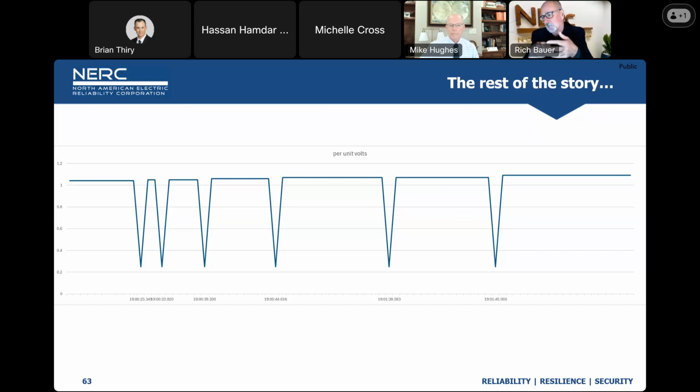After a period of time, I'll automatically reclose that circuit breaker because most of our faults are temporary in nature. They're transient faults. So if we clear the fault, we wait a little bit of time, and then we re-energize, the fault will be gone because it could be a bird, a tree limb. It could be a lightning strike where an insulator flashes over. But the majority of our faults are temporary, so we employ this auto reclosing scheme to just automatically reinsert the line back into service.